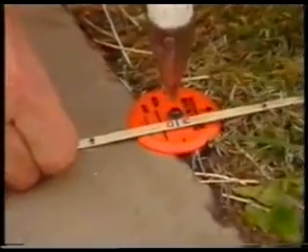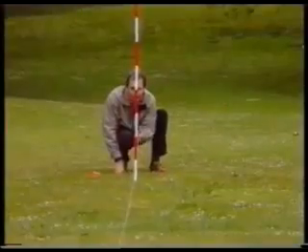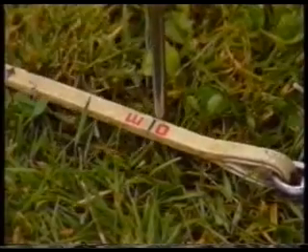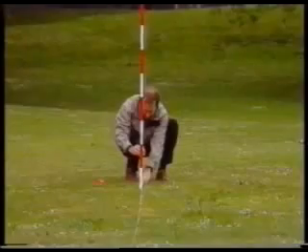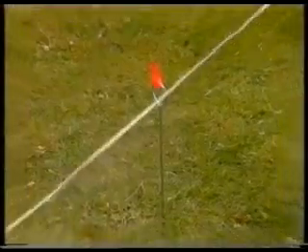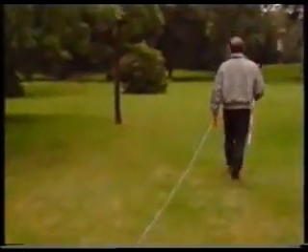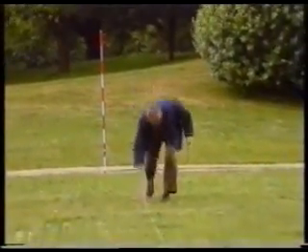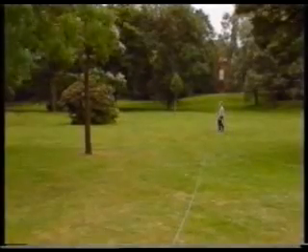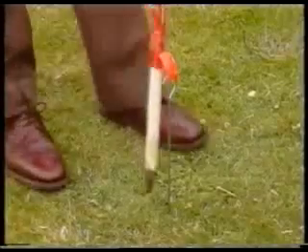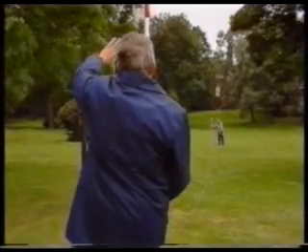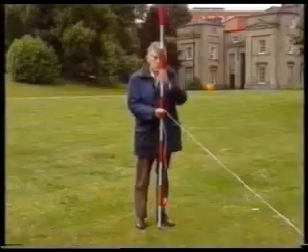The follower holds one end of the tape at point A. It is straightened, pulled tight so that it touches the leader's ranging rod, and the leader pushes a marking arrow into the ground at a complete tape length. The leader then removes the ranging rod and walks further down the line, pulling the tape along. When the follower reaches the marking arrow left by the leader, the whole procedure is repeated to establish a second marking arrow at a second tape length along the line.